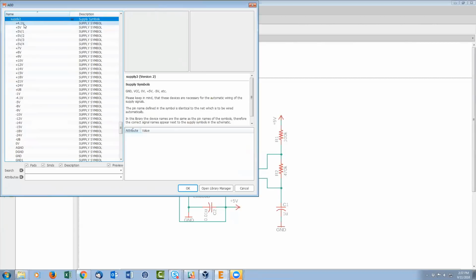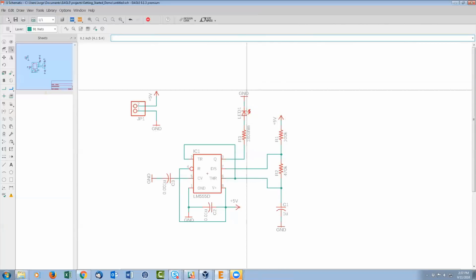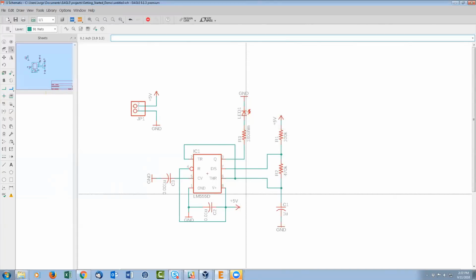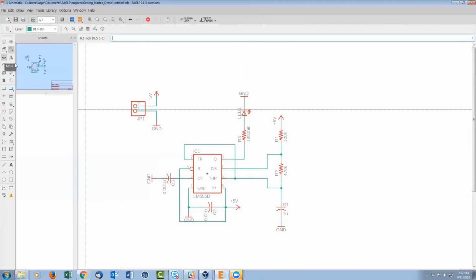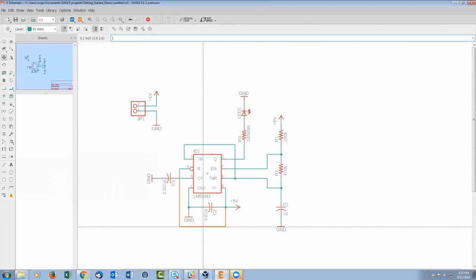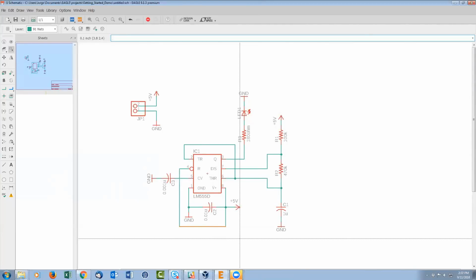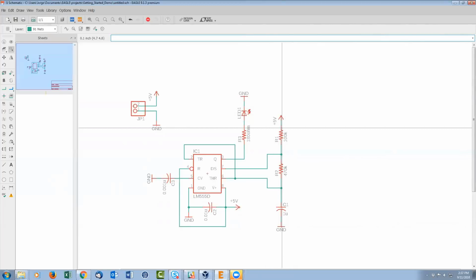Doesn't matter if you rename it on the schematic. And that tends to trip up new users sometimes. Don't associate the name of the component to the functionality of the voltage that has been associated to the actual pin within the library editor directly. Correct. So it uses the device name in the library, not the instance name or the reference designator in the schematic.